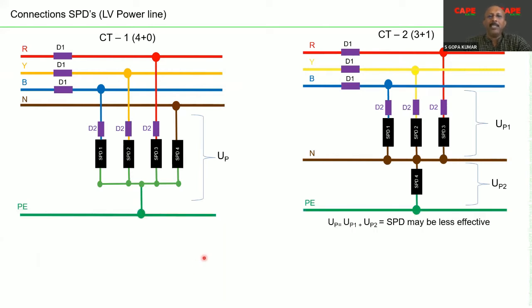It's very easy to understand. If the manufacturer gives a test certificate saying that for connection type 2, between phase and the earth, the device is able to provide a voltage protection level of less than, say, 1.5 kV, you can accept it. If the manufacturer is not providing that particular parameter, you should add the protection level of the first set of SPDs plus the second SPD.